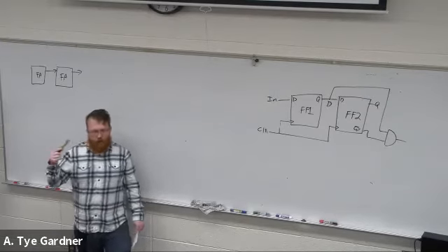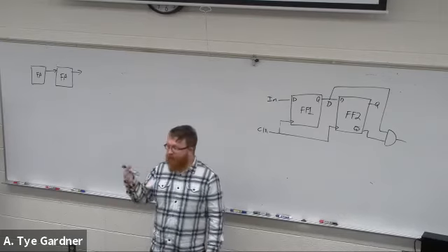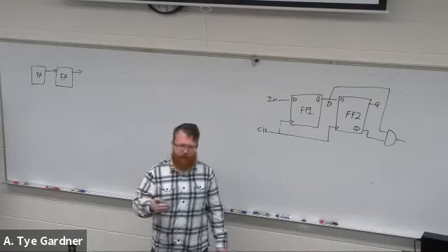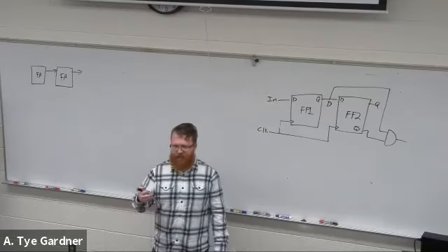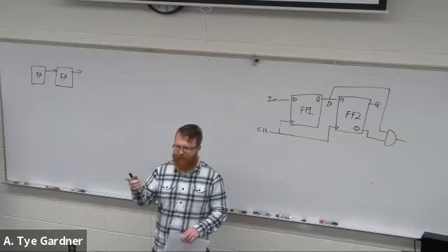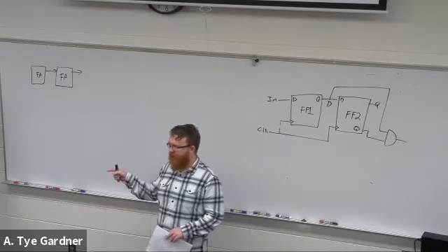So I'm going to walk through something called a carry look ahead adder. The reality is you won't need to build one of these ever in your life because if you write an addition, it will decide whether it needs to be a ripple adder or a carry look ahead adder when it synthesizes.